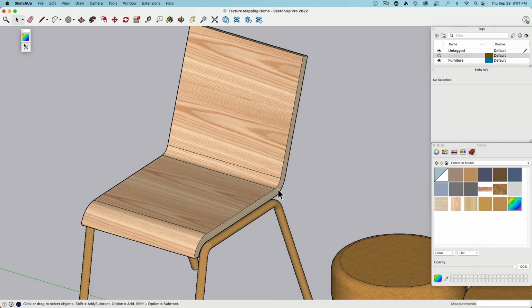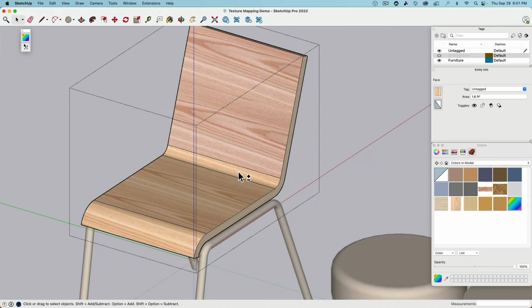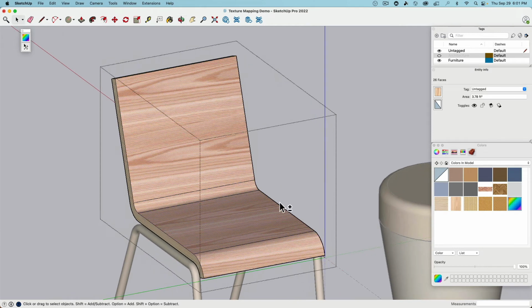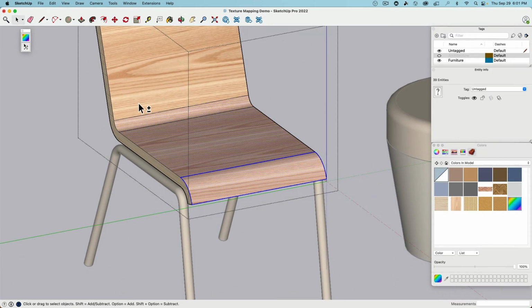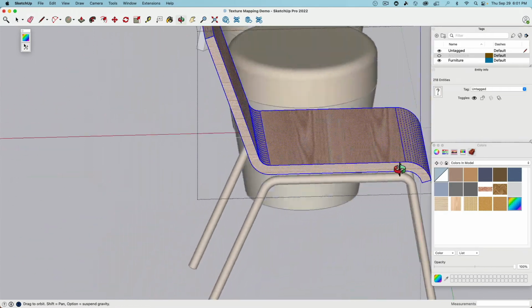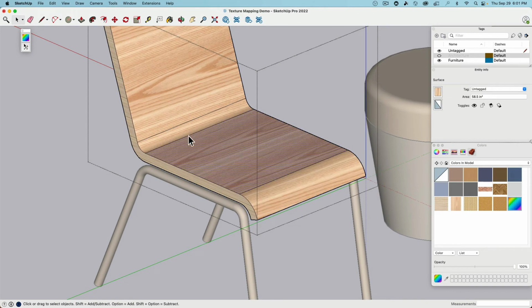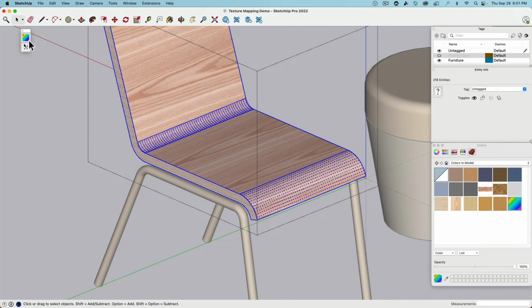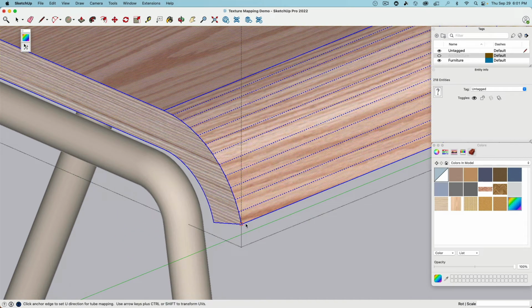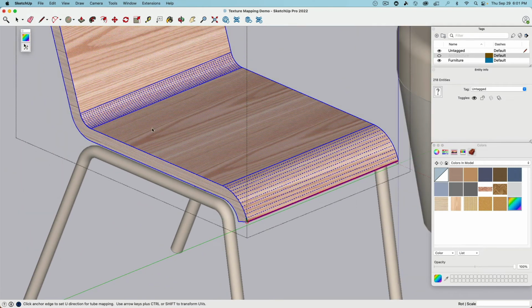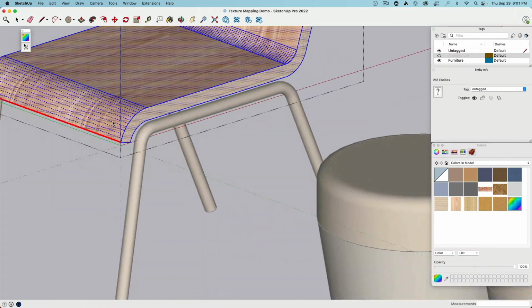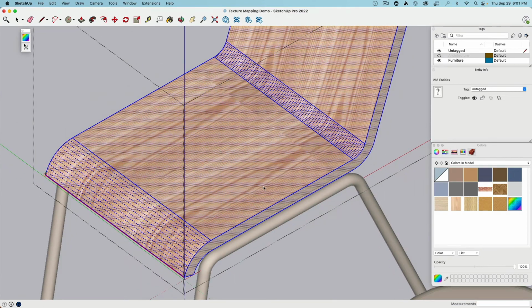Again, pay attention to how this looks right now. And when we select all these faces, triple clicking maybe, there. So you see I selected everything. Everything is selected, so not just some faces, so really everything. Go to UV sketch, click, or here, and right click, tube. Very good.